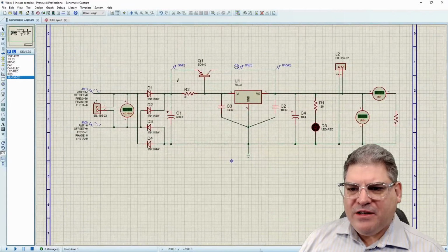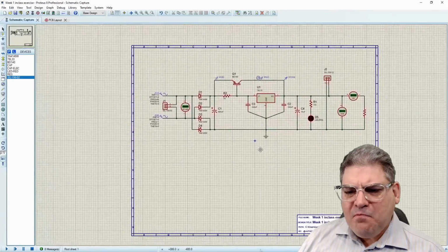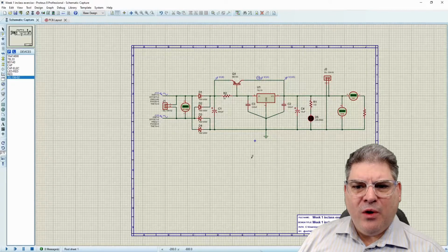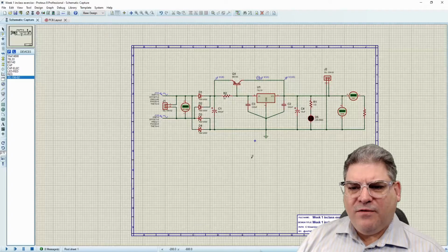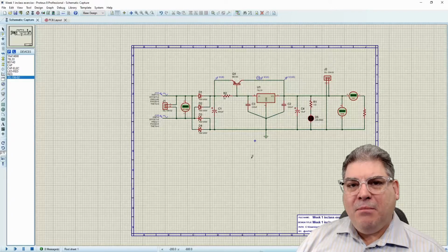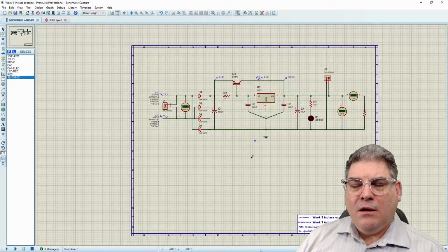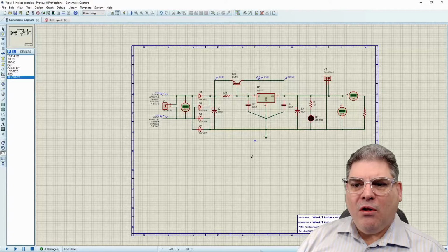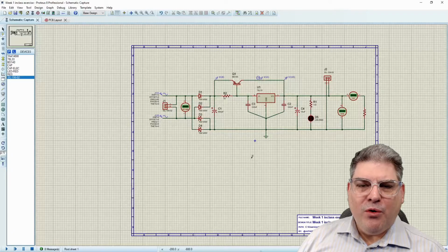I'm happy with this. Let's get ready to print this, and so I'm going to ask for a couple things. One is for some of this stuff, I'm going to want a PDF, and some of it I'm going to want the PSPRJ file, which is a zip file that has all of the design for Proteus in it.